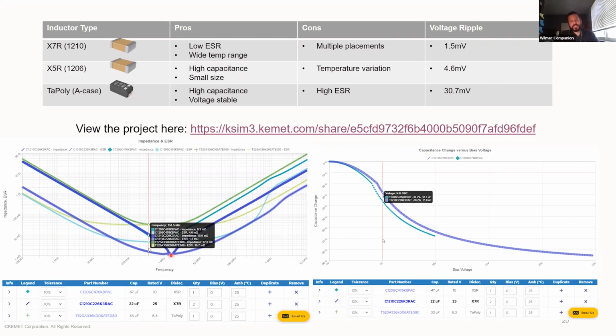So if you were to select 3 capacitors of different sizes, but the same capacitance value, this self-resonant point will be different for all 3 because they have differing ESLs. And that self-resonant point, very quickly, is the point at which the capacitive reactance is equal to the inductive reactance, and those 2 elements cancel out in the impedance equation, and all you're left with is the real portion, the resistive portion of the ESR curve or the impedance curve.